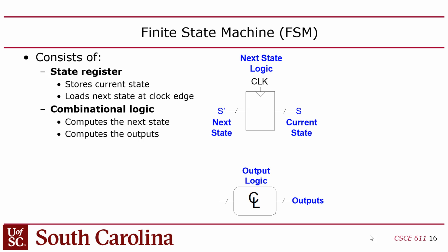It's the clocked part. Those other 2 parts are just combinational. This is the only sequential part of it. Essentially it's just a register where the input is the next state and the output is the current state, right? And of course you connect the reset.